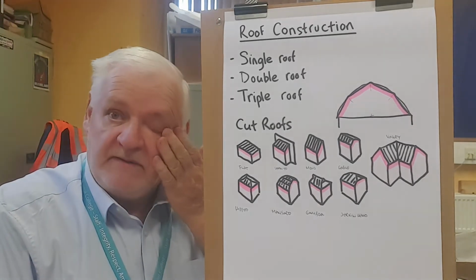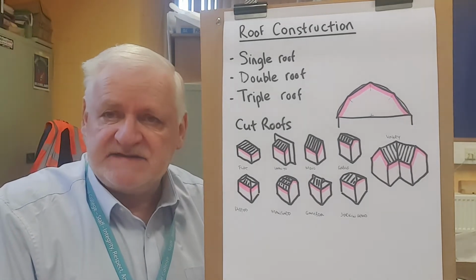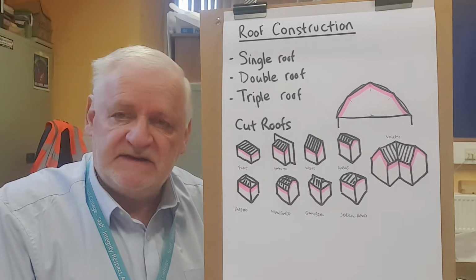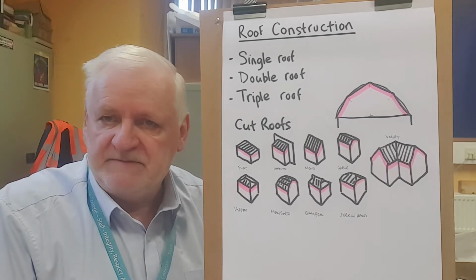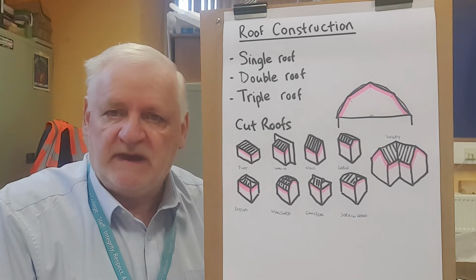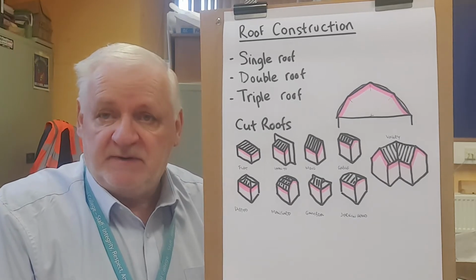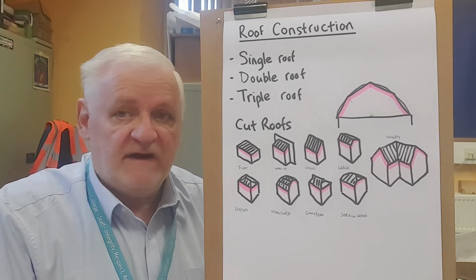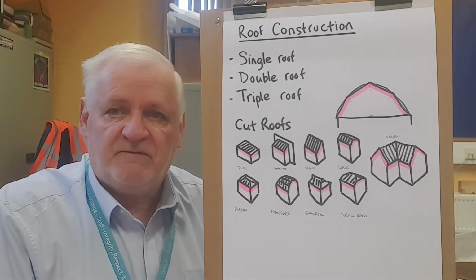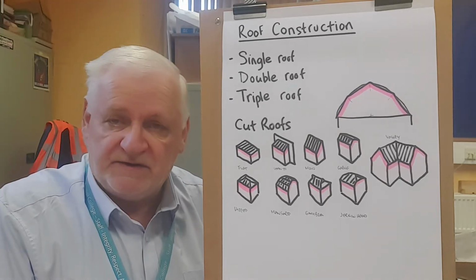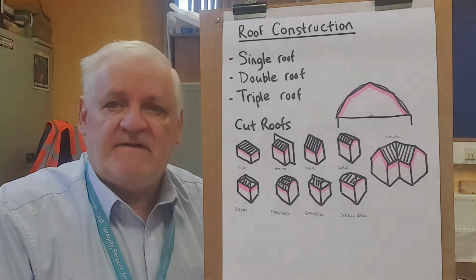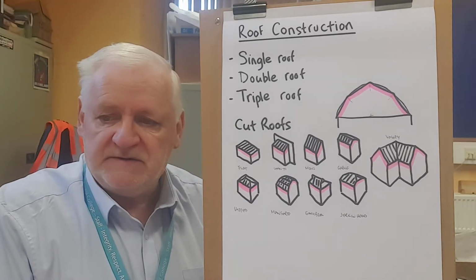And now a superimposed load is exactly the same weight, but we add to it the weight of snow. Generally it's snow that's the one thing that we add to the weight. So a superimposed load then can be very, very heavy indeed. Imagine 4 to 5 tons of snow on top of a roof, and that then is the superimposed load.